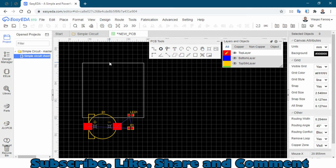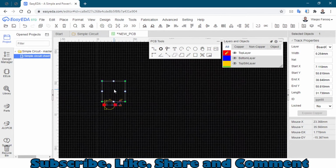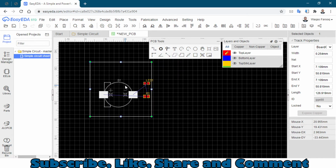As you can see, we have this purple box and all the components here. So I will place this. You can change the size later as well. As you can see, there are 2 white lines. This is the origin, so we have to place this on origin by moving it with arrow keys. Okay, and let's just zoom in. Same process, pressing Control and rotating the mouse wheel.